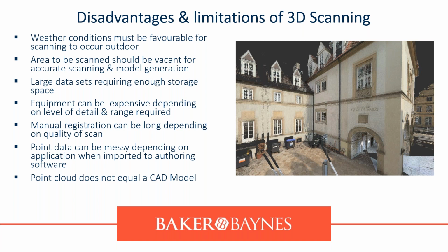And the last thing, I've left it for last, is a point cloud does not equal a CAD model. We always get this question: if I scan the building, do I have my CAD model? No. What you're seeing on the right-hand side are just millions of pixels or dots that are being connected by the laser. It does not equal a CAD model. You will still need to import it into the software and model it. Alternatively, you can use various technologies to auto-extract it, like I've done for this webinar. The one I've used is ClearEdge EdgeWise by Topcon, but you'll have a look at it now to see how awesome it is.